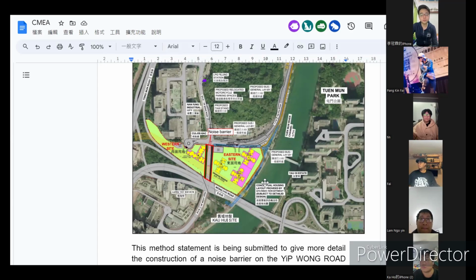There are approximately 190 meters of noise barrier to be constructed as marked in the plan. All welding work will be completed in the daytime in the site area. All transportation of required material will use lorry cranes, and work at height will use a system platform.